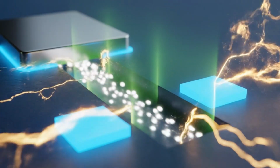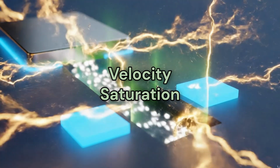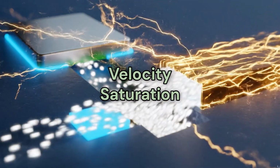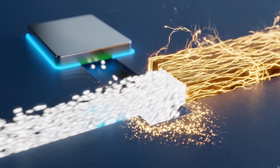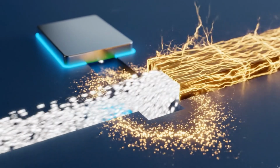In short channel MOSFETs, as we scale down to nearly 100 nanometers, velocity saturation occurs. Carriers can't accelerate indefinitely due to scattering, limiting current despite increasing electric fields.